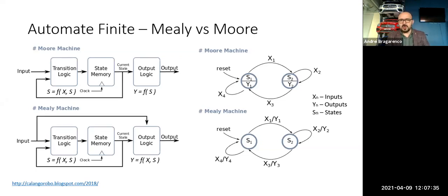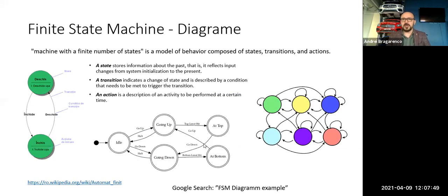The difference between other systems and a finite state machine is that it defines a behavior, and when we define or change the behavior of a system, even a small change, we should redesign the whole diagram. We cannot just scale it, one sensor, many sensors, or one state, many states.